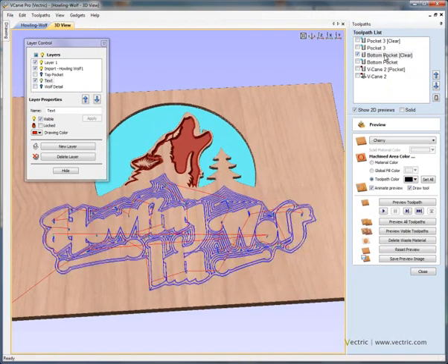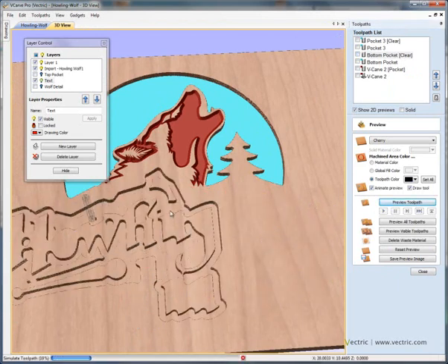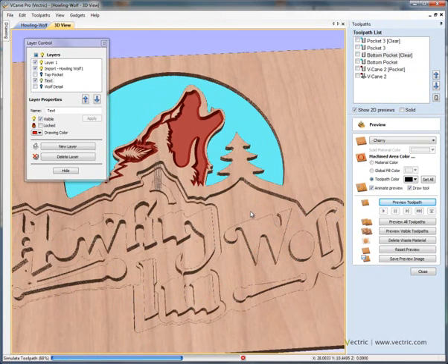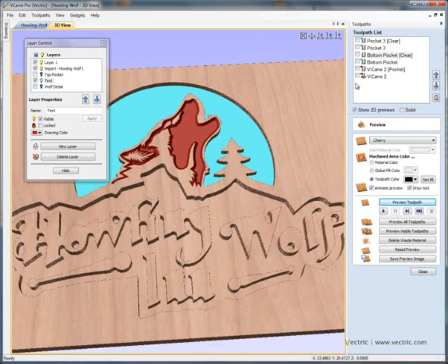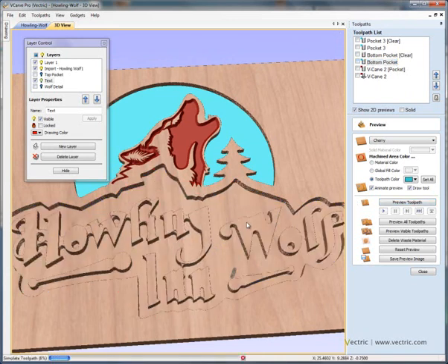We've got the 1/2 inch end mill toolpath. Preview that. So this gets rid of as much material as we can, as fast as we can. And then we change the cutter to the 1/4 inch bit. So this is going to profile machine around. Preview that toolpath and pick out some of the detail around the lettering. So this is going down in small incremental steps.